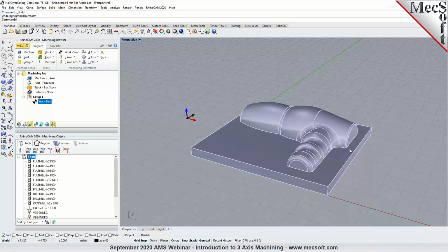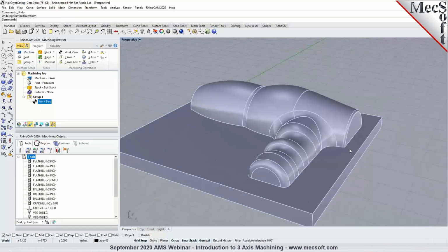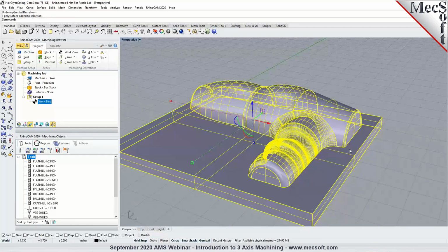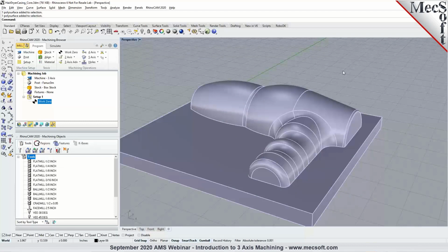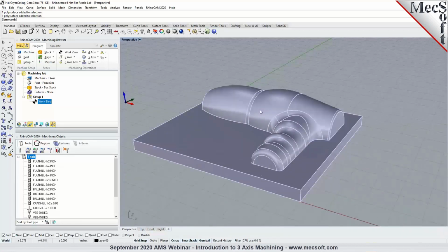We could work with solid geometries, which could be made up of a bunch of surfaces stitched together, which would be a poly surface. In this particular example, you're seeing a poly surface where multiple surfaces are joined together, which forms a closed poly surface, or it could even be an open poly surface. You could program 3-axis toolpaths for geometries that are both closed or open poly surface.